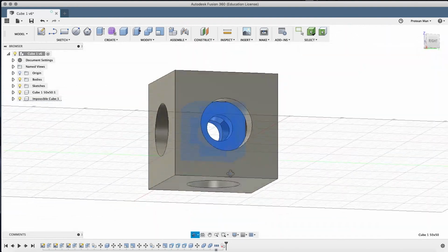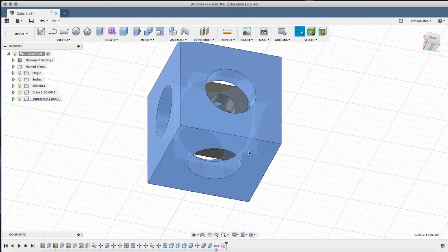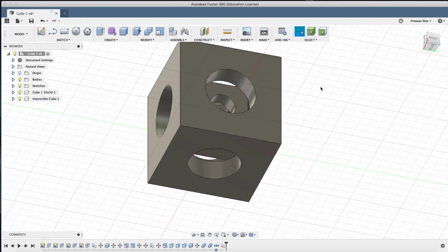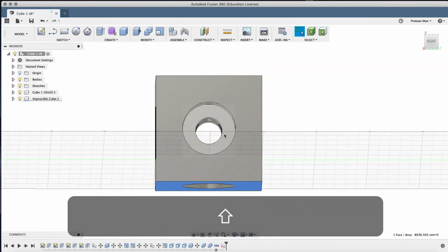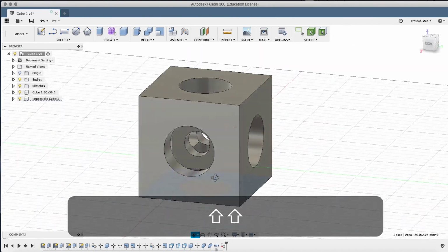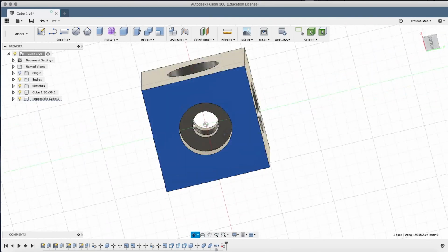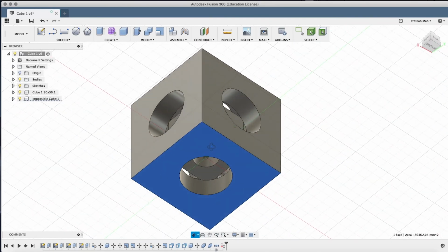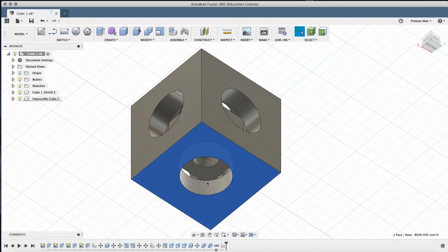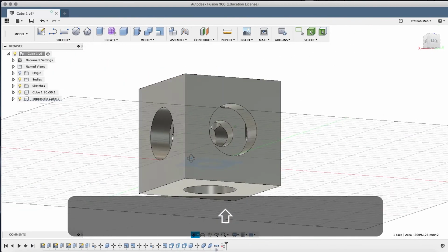If the ground is this plane here, the bottom area here, this middle cube has no attachment to the ground. So you can't print in midair, so a slicing program for 3D printers will add what's called supports. Whatever design it is, whether it's squares, circles, or sort of a fan-looking layer, it will add those to help support and build it up until it hits the bottom of this, and then it will print the normal parts of it in the middle of the cube, the center cube.